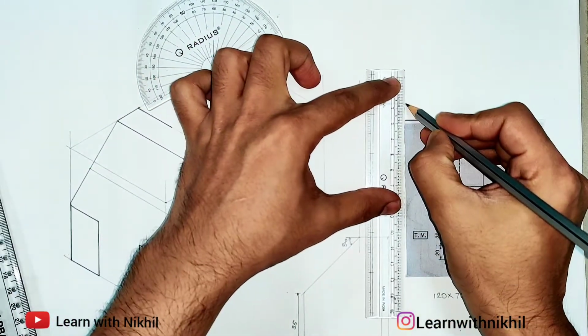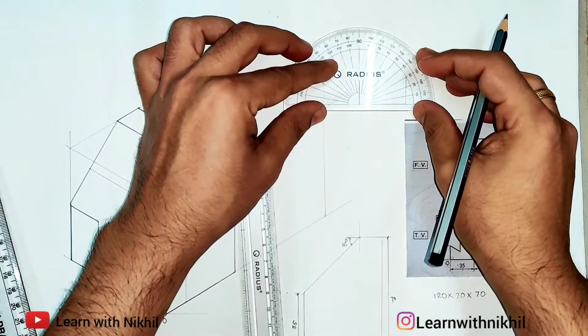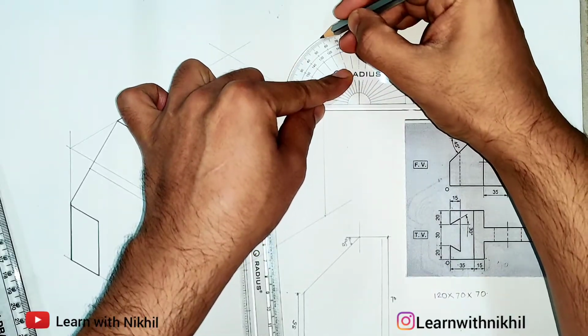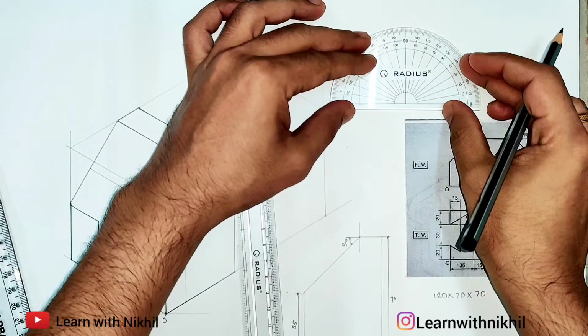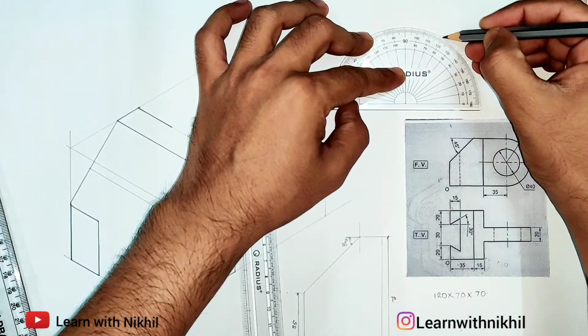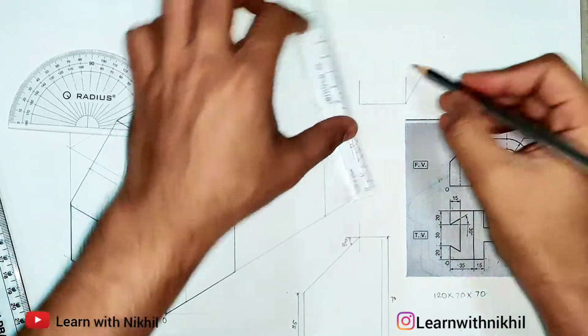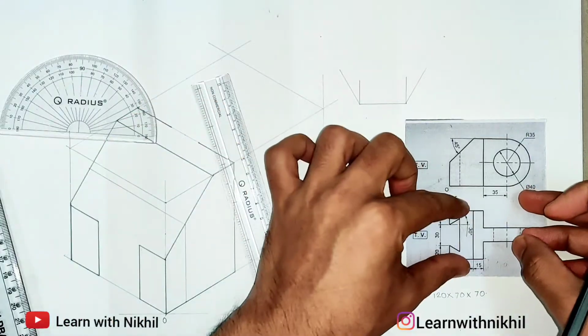So first I'm marking the perpendicular line, so it will be easy for us to plot. So from the perpendicular line, from here 30 degrees, so this is 30 degrees, and from here also from top 30 degrees, so this will be that. Drawing here lightly, I'm not extending till the point as we just require a little part.